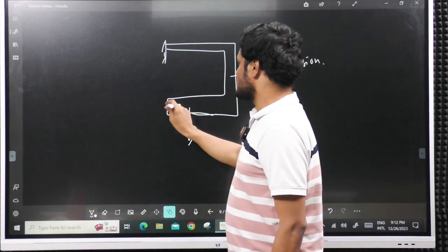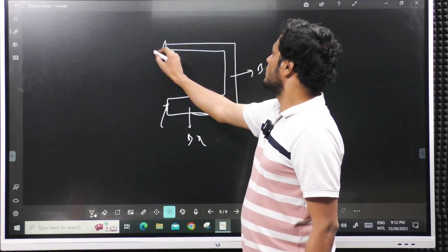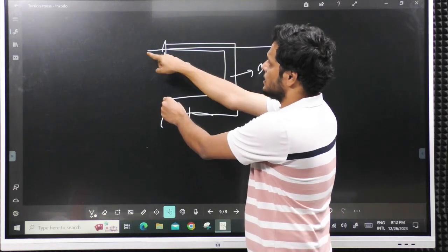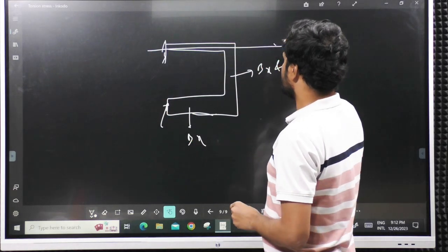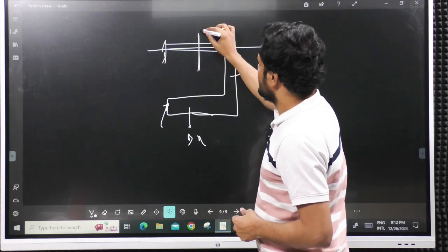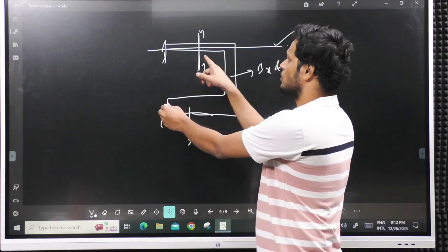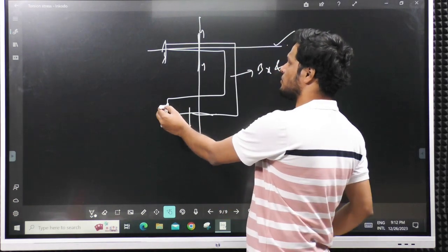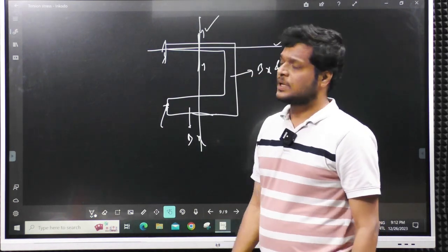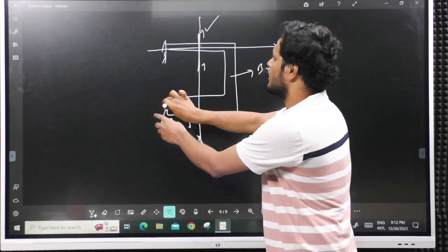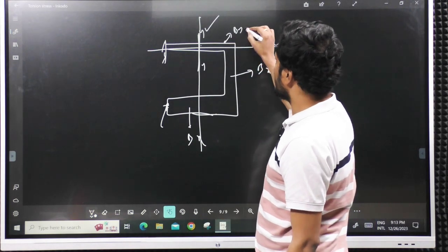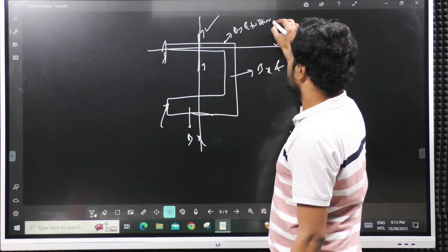Okay. Next, third one, okay, load lying out of the plane. Okay. So the load is lying out of the plane, it cannot meet even on extension, it cannot be parallel even on extension, so it is having torsion for sure. Okay. Now take any cross section and draw remaining two axes. Y axis, is it meeting? No. Even on extension it won't meet, is it parallel? No. So obviously it is bending about y. Next, bending about x, x-axis is parallel to this, so you can directly eliminate the axis. So, this is bending about y and twisting as well, or torsion, both are same.